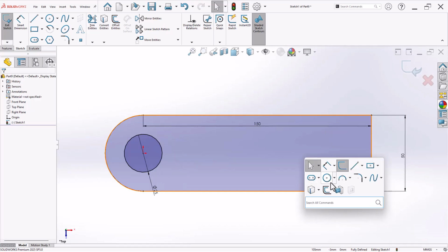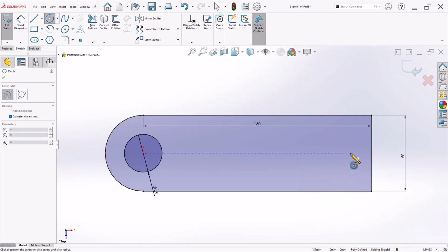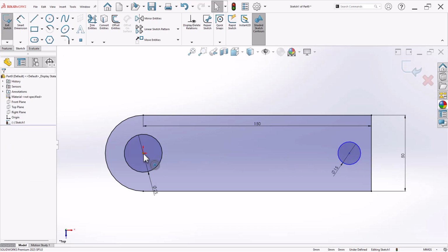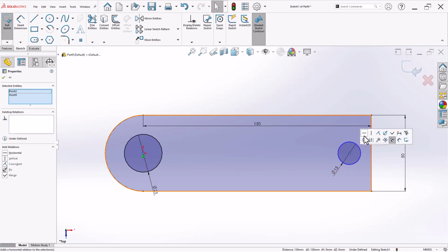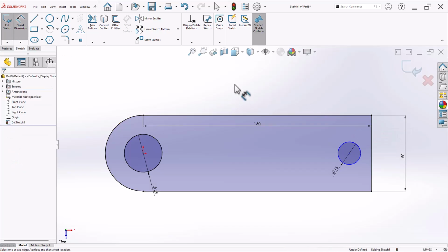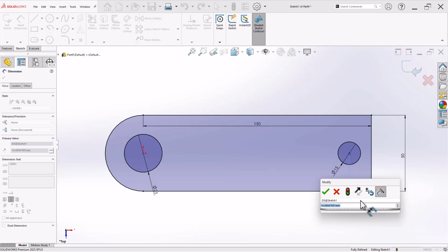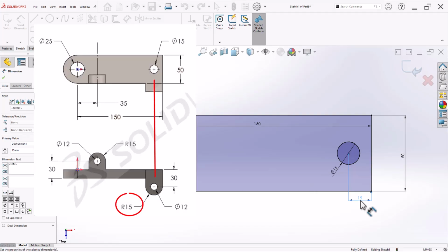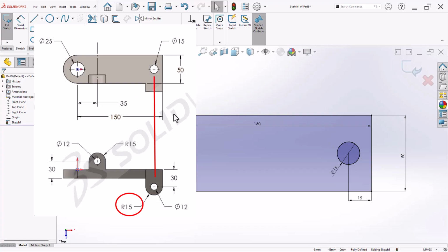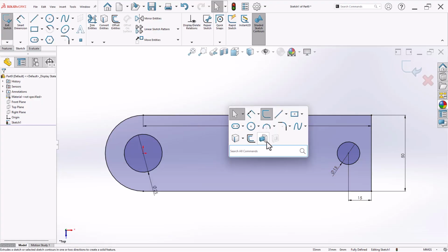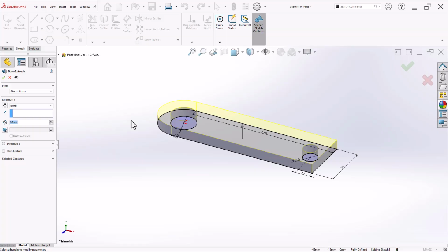Let's also drop few circles here. One more circle having diameter 15. Let's make them a line. If you look very carefully, its dimension of center from the edges is 15. It is aligned with this bracket hole. Now let's extrude by 15.